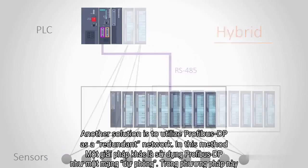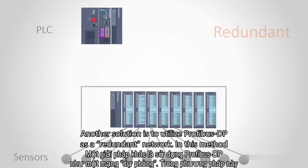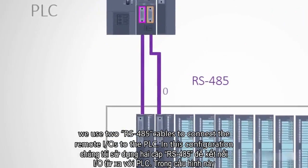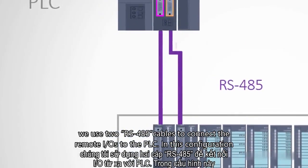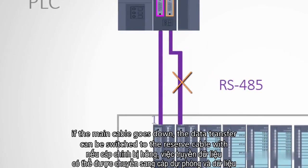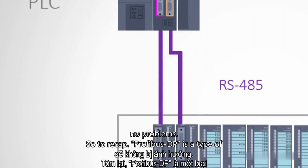Another solution is to utilize Profibus DP as a redundant network. In this method, we use two RS-485 cables to connect the remote I/Os to the PLC. In this configuration, if the main cable goes down, the data transfer can be switched to the reserve cable with no problems.